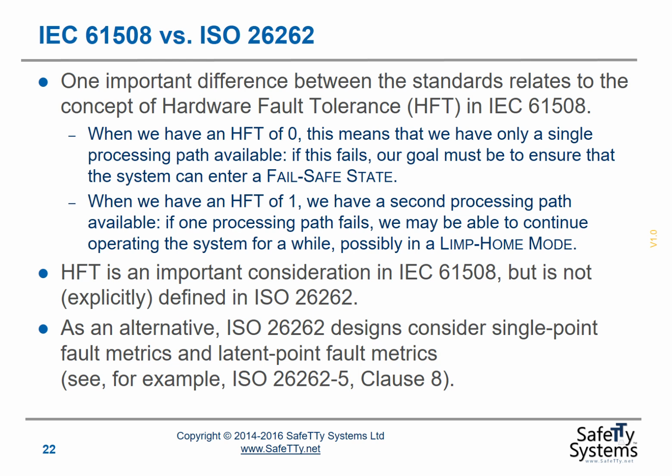HFT is an important consideration in IEC 61508, but it's not explicitly defined in ISO 26262. As an alternative, ISO 26262 considers single point fault metrics and latent point fault metrics. Please see the standard ISO 26262 Part 5 Clause 8 for further details of this.